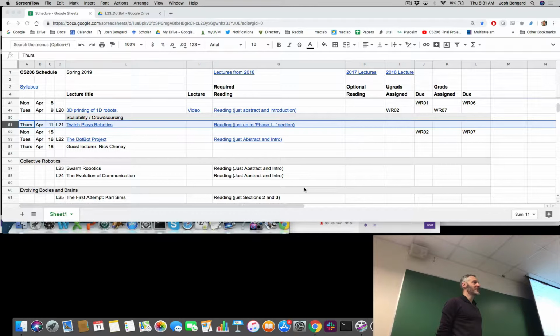Exactly. So you got a lot more variance and uncertainty when your system is computing the fitness of a given controller, right? You might drop a controller into the robot, it's in a particular environment, and given the situation of that certain environment, that controller gets lucky. On average, that controller will perform badly, but if you only evaluate that controller once in a random environment, it might get lucky. Or vice versa, you might drop a controller into the robot that, unbeknownst to you and unbeknownst to your evolutionary algorithm, will on average get the robot to perform pretty well, but it happens to be placed in an environment that's particularly difficult and fitness is returned as being a relatively low value. So now we have this added challenge about trying to estimate the fitness of a controller on average.